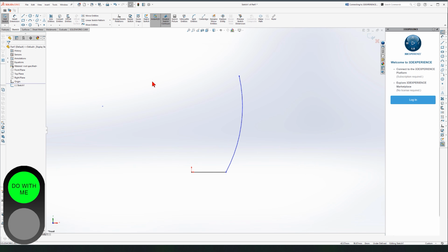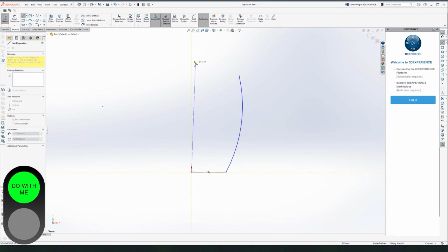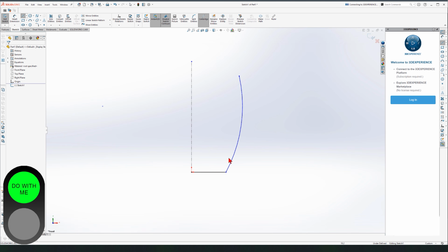So I'm going to repeat the last few steps on the green light again. Clicking on this arrow, activating center line, click on this point, snap vertically up. One of the signs that I see I'm vertical or not is this yellow symbol that appears next to my mouse.